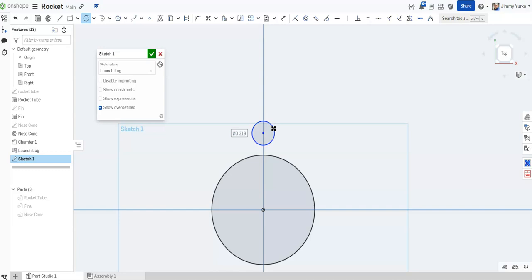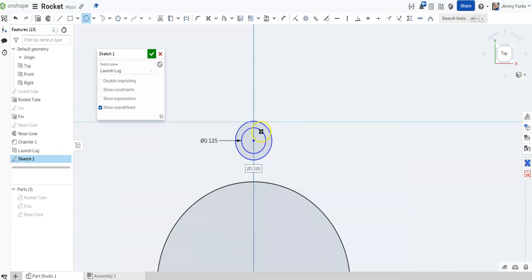The inside of that tube is going to be at least an 1/8 inch, but not a whole lot bigger. And then the outside of that tube is going to be slightly larger than that, whatever the thickness you have, so you can measure that for yourself. Last time we measured diameter and diameter. Let's go ahead and measure the distance between them this time. So click on this one, and you can see we got a distance between, and we'll go with 5 thousandths, 0.005.